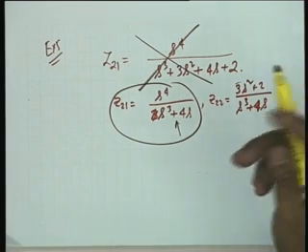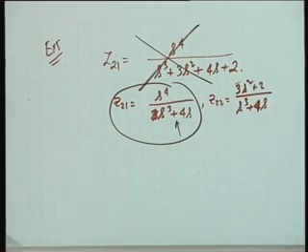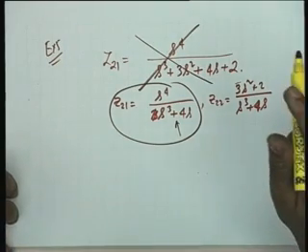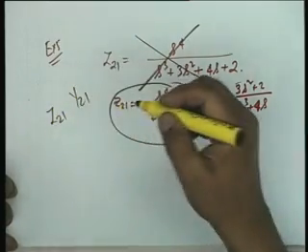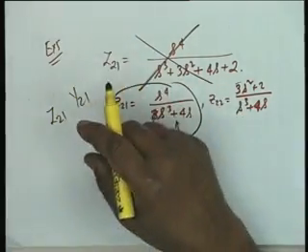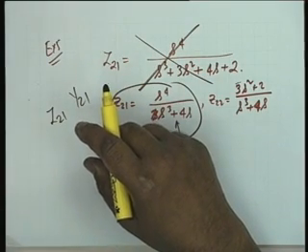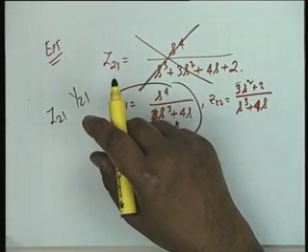We will take one example in the problem session of synthesis of resistance terminated ladder, but the caution that I want you to exercise is, please pay attention to whether it is a Z21 or Y21. That is, whether the last element that you develop will be in series or in shunt.